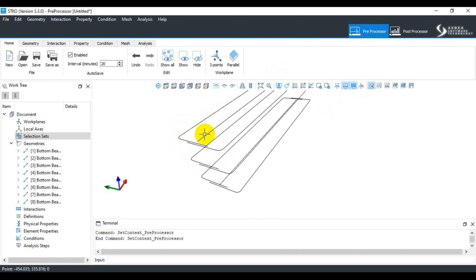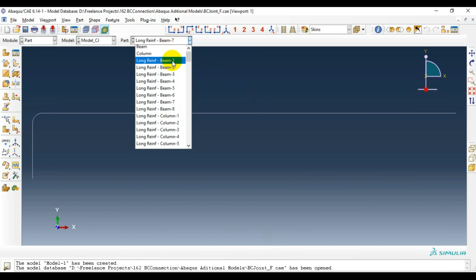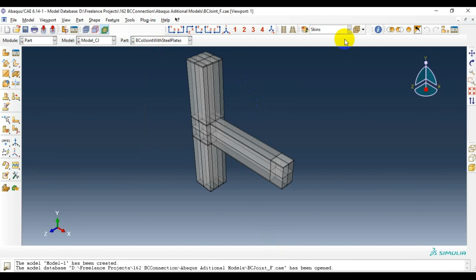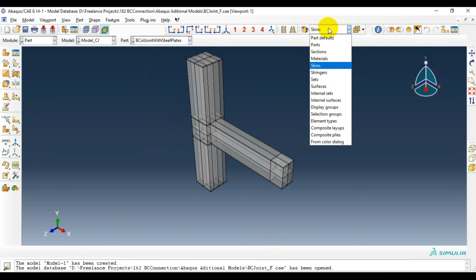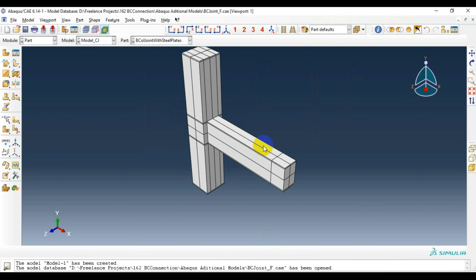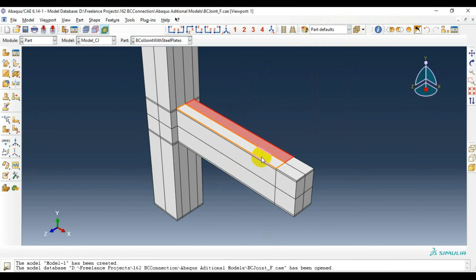We can see that if we have the edge option on, we can select them one by one. But since we have hidden the options that are not available for us, we can do select face here as well. This option is available in Abaqus if we are working with the geometries. Then in the display groups we can do that in our analysis environment property. So let's say I want to select any face, I should hold shift with it, right?